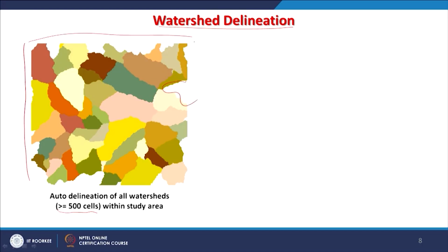which you can see. Because remember, one watershed ends, another starts. Here we do not have a continuous digital elevation model for the entire globe, only a part of it. So this area will contribute to some other outlet, maybe like this, not here, and therefore it is not part of this basin, and it has not been delineated. Similarly in all boundary areas. That means the water will flow out like this, and the same here also.